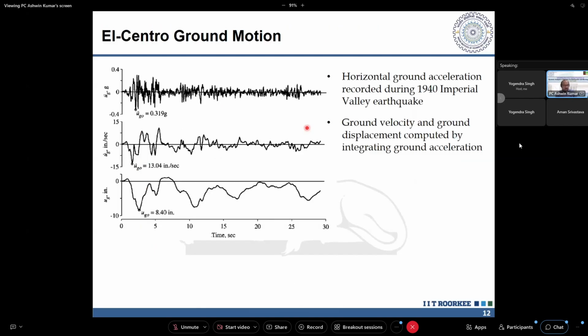So till now, whatever we have seen is what you start with at the beginning of a theory of vibration class, wherein you look at a single degree of freedom system. You do the free vibration analysis to get the natural characteristics of the system, that is the natural frequency or the time period. Then you have the forced vibration problem, where you have p0 sine omega bar t, or a step function or an impulse function, and you use the classical approach of the particular solution and homogeneous solution to find the displacement time history of the system, right? That is what we have covered till now. That is what I have summarized.